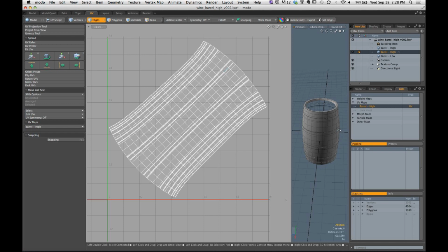Okay, let's do one more thing. I want to select your geometry, and I'm going to do a mesh cleanup. There were a bazillion floating vertices on your mesh, one-point vertices. Specifically, there were 144 of them. That may have been your problem. Mesh cleanup magically fixes a lot of different things. Let's try. Yeah, that was it.